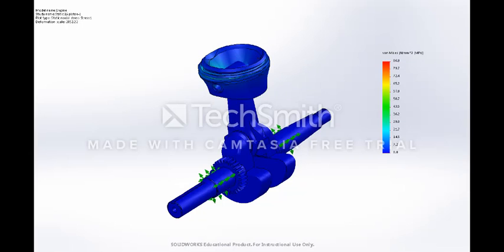temperatures. The load was applied to the inner face of the cast iron piston, while a hinge fixture was applied to the connecting rod elements. As a linear analysis, the temperature load increased stress and displacement appropriately.